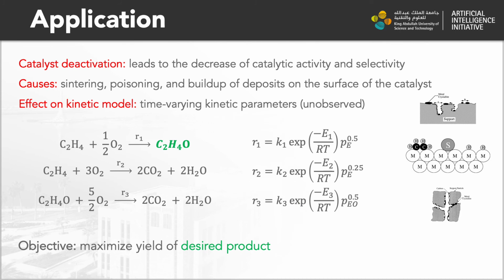We have applied our framework to the oxidation of ethylene to ethylene oxide. This reaction resembles many industrial processes wherein a metal-based heterogeneous catalyst is used for a complex gas-solid reaction. In such environments, catalyst deactivation occurs and it is caused by various mechanisms such as sintering, poisoning, and buildup of deposits on the surface of the catalyst. This deactivation not only affects the catalytic activity and selectivity, but it also means that the kinetic model we started with is no longer accurate. Hence, model-based control and optimization will not be as effective.